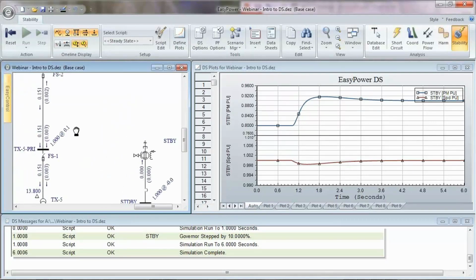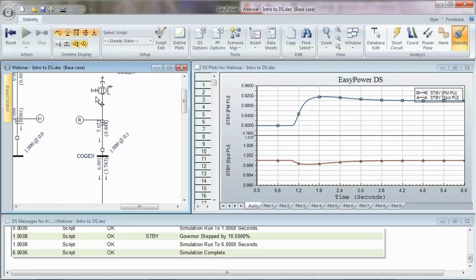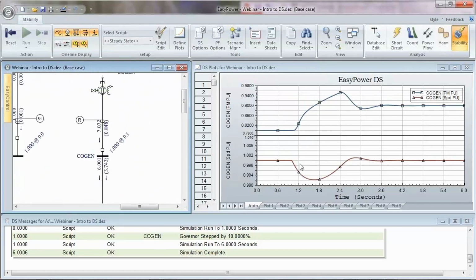Whereas in the other one, we had steady state droop. Oh, do you know what? Not this one either. This one must be a form of isochronous as well. But you could have it in droop mode if you wanted to. Droop mode means that with a step load and power, we would see the speed drop slightly.